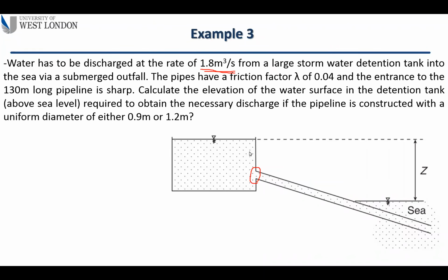If it's very close to sea level, we may not be able to discharge this. And bear in mind, we have a pipeline system, and friction head loss happens, and we have an entrance head loss, and we need to see what other head losses we have.